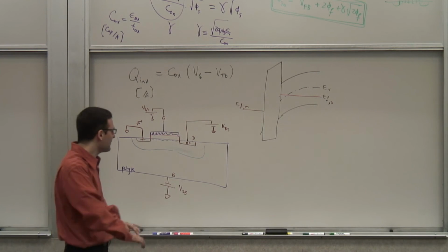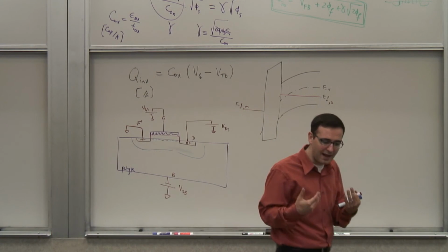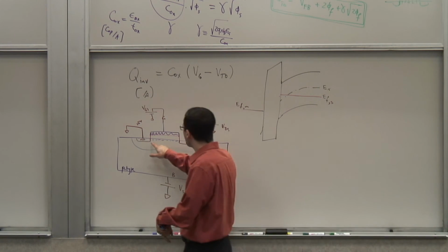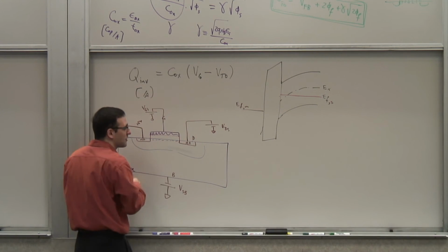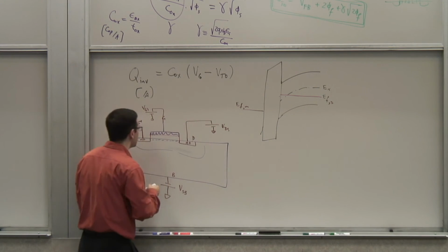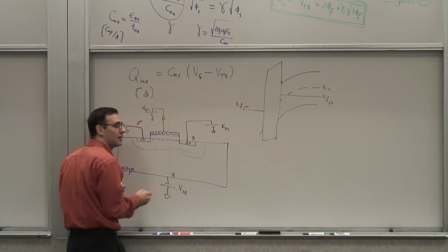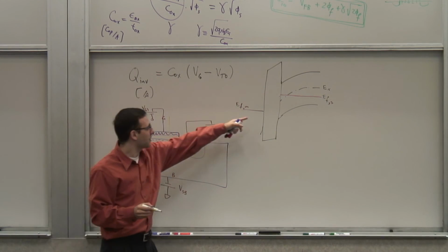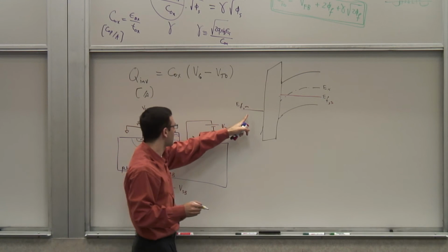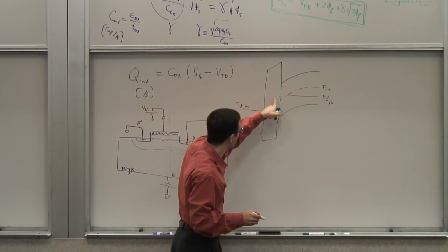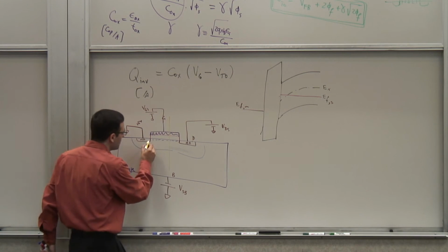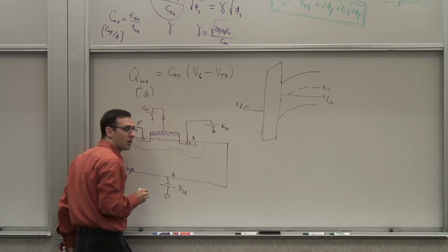Okay. So that's a very simplified picture. Now, from an energy band diagram picture, you can also look at this. I can draw the energy band diagram in this direction. Remember, that energy band diagram is along this axis, right? Starting from the metal, well, the conductor, oxide, insulator, and semiconductor. Now, I'm going to draw the energy band diagram along this axis.